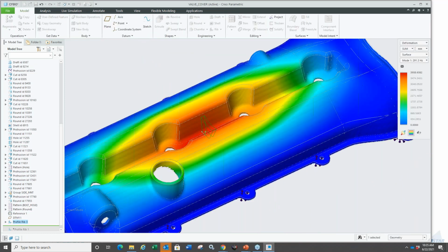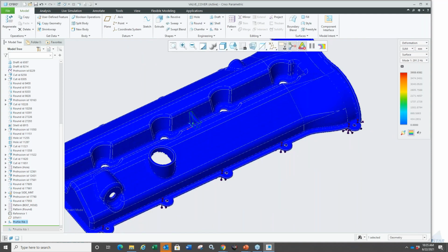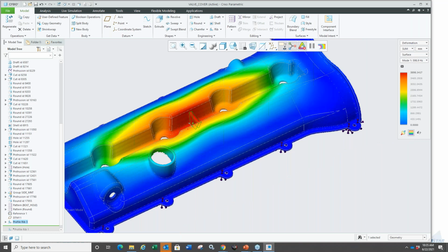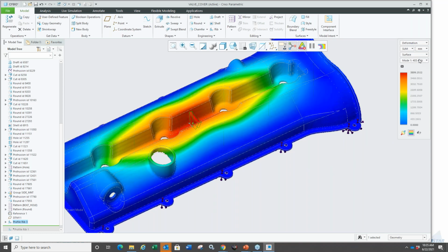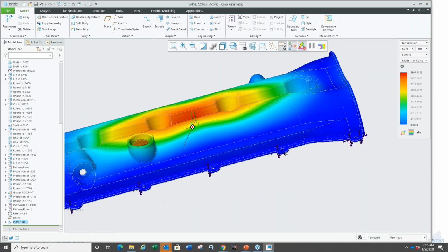So as soon as I'm done with it, again, the software should go back and recalculate the natural frequency for me, right? It came down a bit, or it's increased, let's see here. It's still settling. I need to allow it to settle in a little bit there. It's, what is it, 370, 360, you're avoiding 300, but it's still, maybe it could be, now I know that direction, right, that those ribs are helping.